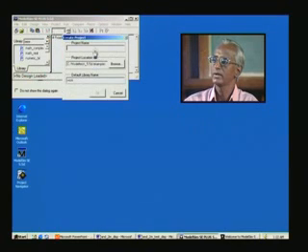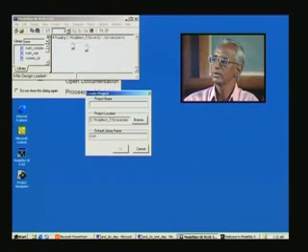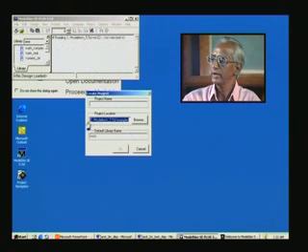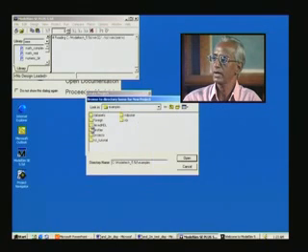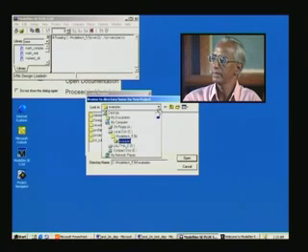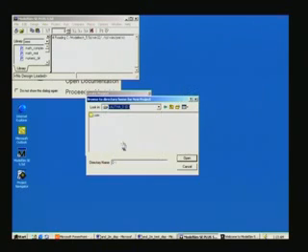We just click, and you see here there are two windows, and what you have here is a project name you have to give. This corresponds to the create project that we saw in this menu. And you see here a project location. It's good practice to go to where exactly your design files are residing, and in order to do that, you have a browse. Another window pops up, and here it is in this directory: user, then RAM, then VLSI design, etc.